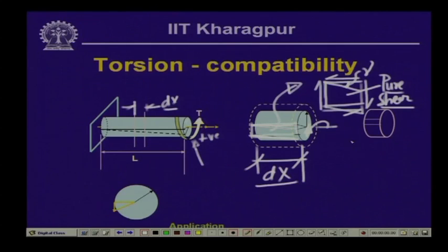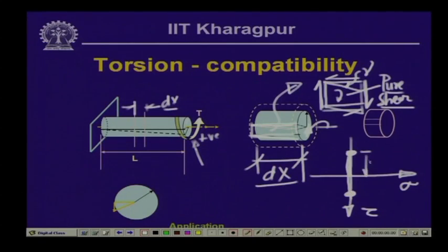Now, if you remember, if we plot this state of stress in the Mohr circle, this is the sigma axis and this is the tau axis. Now, here we have negative, because this is clockwise movement by this particular shear on this face. So, as per our notation, this is a negative shear which is plotted on the top side of the Mohr diagram, and for the other side we have a positive value which is plotted over here. So, this is the value of tau, and if we plot it as a circle, this is the center.